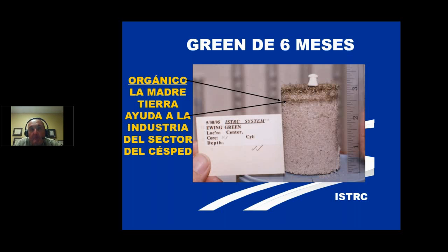I'll give you an aside. When I look at the physical properties and the balance of infiltration rate to air porosity to water porosity, the infiltration rate to me is more than just a direct measurement of the ability of water to penetrate the surface and flow through the sample. It is also an indirect measurement of how easily oxygen can penetrate and reoxygenate the soil itself. And so it gives me an indirect measurement of the ability for the aerification.